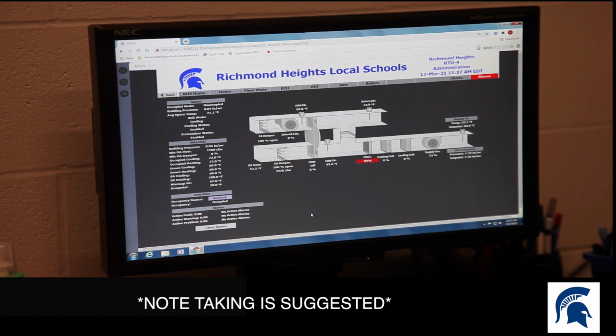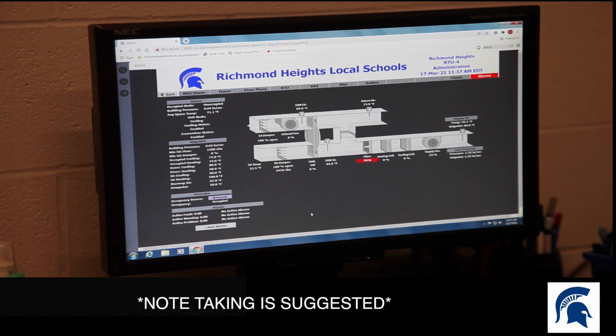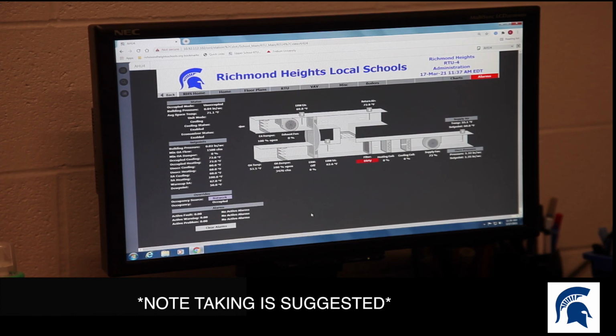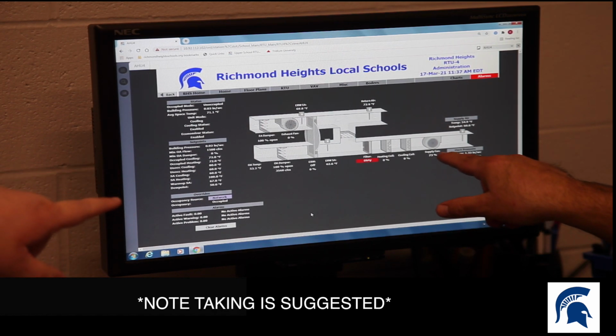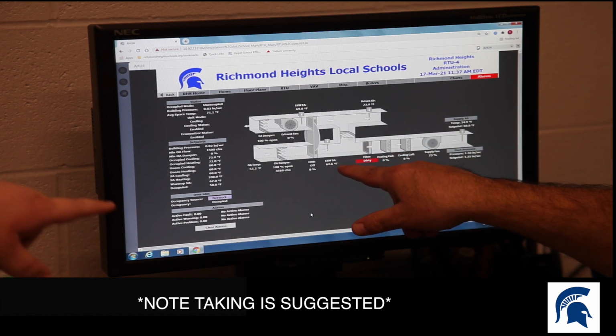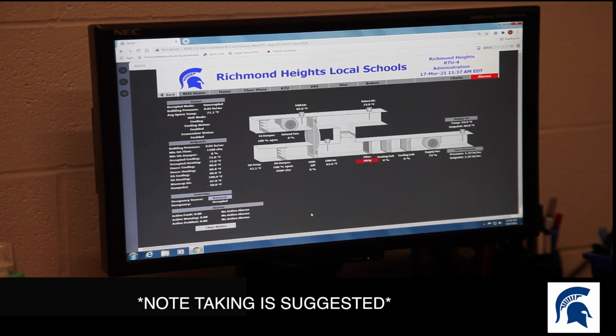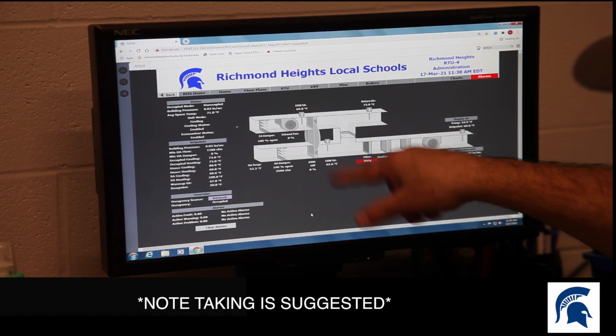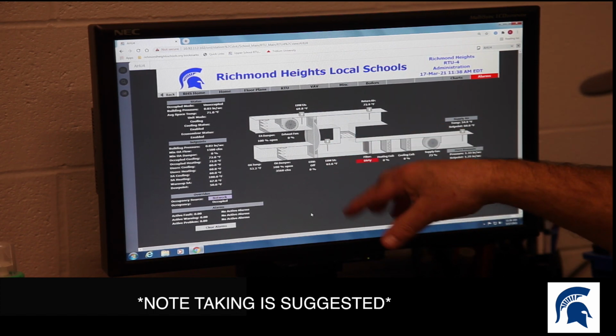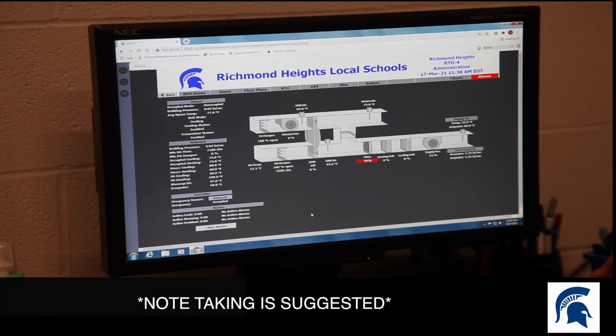So what it's trying to do is use your outside air, because you're 100% open right now. If you look at the other side of the wheel, your supply air coming out of the wheel is still 62.6 degrees, which is above your 60-degree supply air setting. So that's why it's bringing on the cooling, because when it's going through that, the wheel is recovering heat. Well, the wheel is disabled right now.